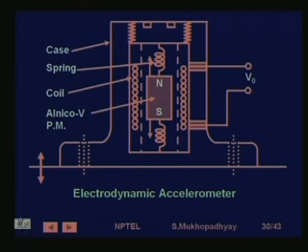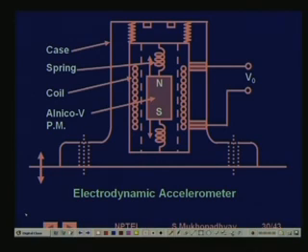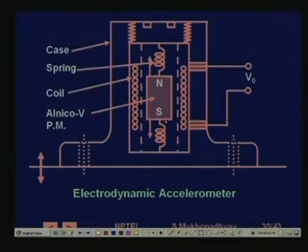accelerometer. Acceleration sensing is mainly used in the industry in the context of vibration sensing, which is a sensor which is widely used, especially for maintenance and fault diagnostic purposes in all kinds of machines. So piezoelectric sensors are basically, in a way, acceleration sensors. That is the biggest class of acceleration sensors which are used, but just for a general principle, this is